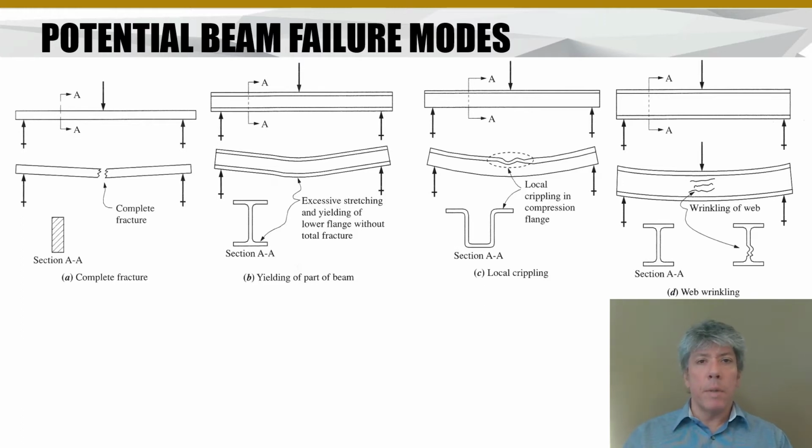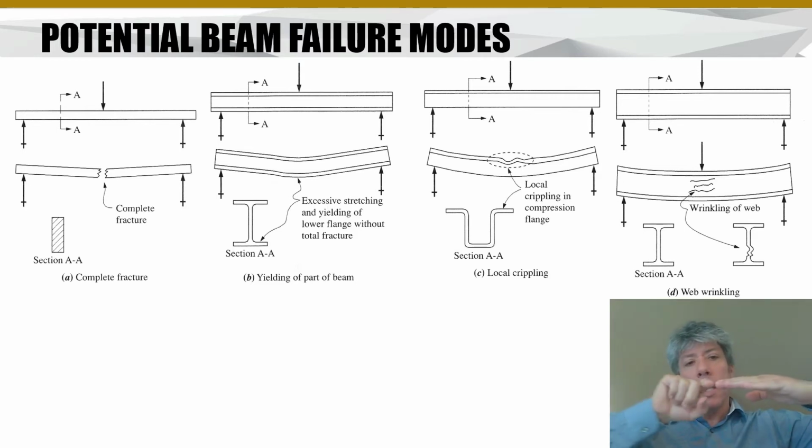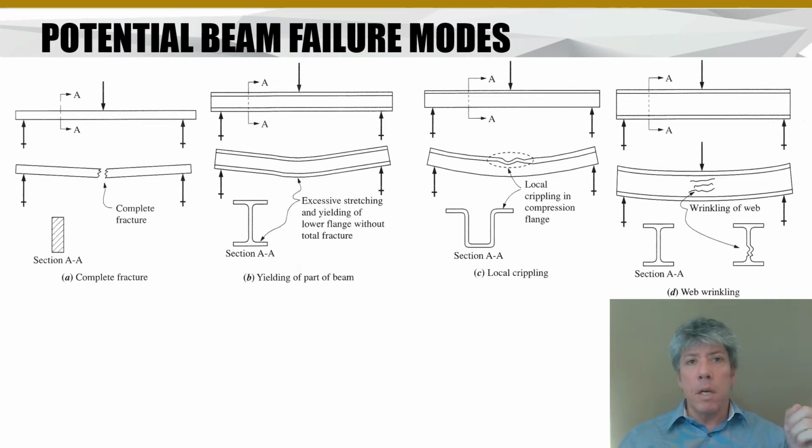In fact, in a beam, what causes failure most often is the moment load within the beam. And you can think of the moment load, remember we had shear and moment diagrams, you can think of the moment load if you want to understand it. Imagine that there's a hinge somewhere in the beam. So the beam flexes, okay, so it's got some hinge point in it. The moment in the beam is the amount of torque at that hinge that would be required to keep the beam from moving down, see? And you can imagine a hinge at any point along the length of the entire beam, and however much torque is required at that hinge to keep the beam horizontal, that's the moment in the beam.